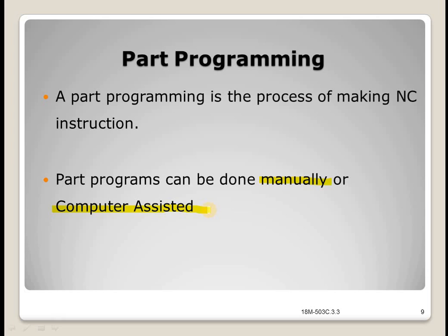The part programmer can create the geometrical model in the CAM package or directly extract the geometrical model from the CAD/CAM database. Built-in tool motion commands can assist the part programmer to calculate the tool paths automatically. The programmer can verify the tool paths through the graphic display using the animation function of the CAM system. It greatly enhances the speed and accuracy in toolpath generation.